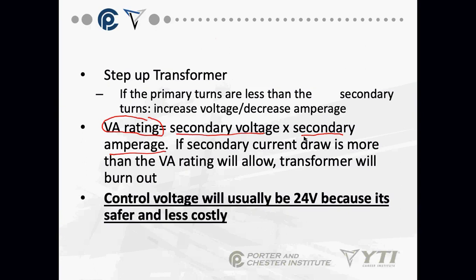So if you go into a supply shop and have to buy a transformer, you have to know the primary voltage, you have to know the secondary voltage, and you have to know the VA rating of the transformer you need. And they look a lot the same, so you really have to look at the boxes. And just as a hint, always open the box and look at the actual transformer, because sometimes people return wrong things in wrong boxes. So you always want to look.